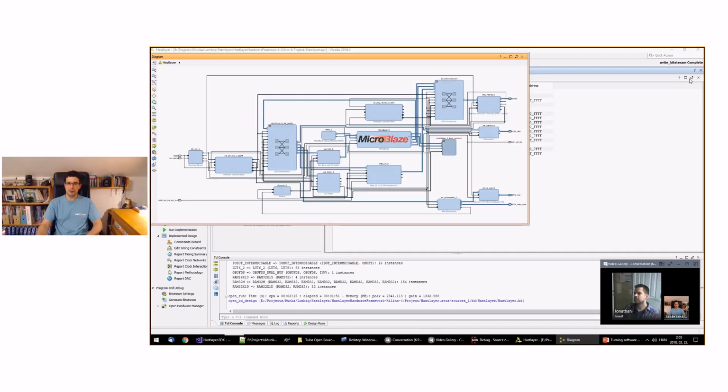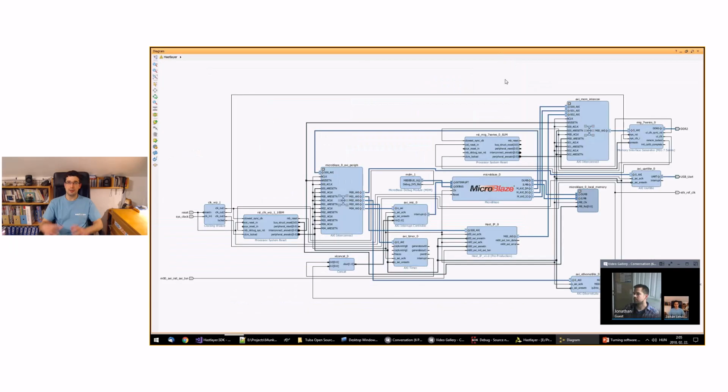The short answer is that we build everything ourselves, and that's then programmed onto the FPGA. What we see here is a high-level overview of the design that's on the FPGA, including the generated component that we plug into this, this Hast IP. As you can see, we also have a MicroBlaze software processor in the middle. This whole framework on the FPGA is configured via JTAG. There is no prior configuration needed, no specific jumper configuration or anything like that.